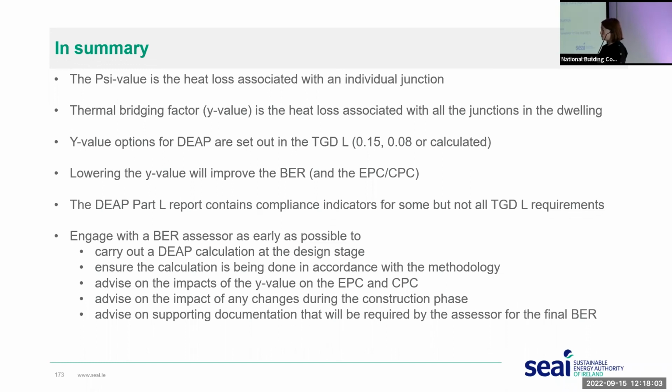The DEAP Part L report contains compliance indicators for some, but not all, technical guidance document requirements. And it's important to engage with a BER assessor as early as possible to carry out the DEAP calculation at the design stage, ensure the calculation is being done in accordance with the methodology, advise on the impacts of the Y value on EPC and CPC, advise on the impact of any changes during the construction phase, and advise on the supporting documentation required for the final BER.